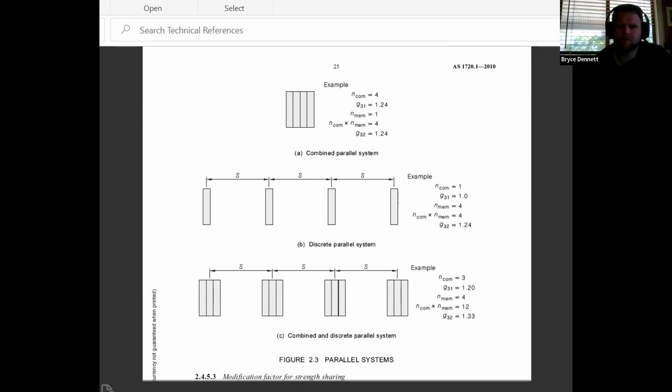Okay, fair enough. I mean, you get double the strength because you've got two beams. Yeah. But if you're using natural timber, you'd get double the strength plus the 14%. Yes. Okay. Yep. So when you come to LVLs and glulams, the strengths are higher than the timbers they're made out of because of that averaging, because of this K9 effect.